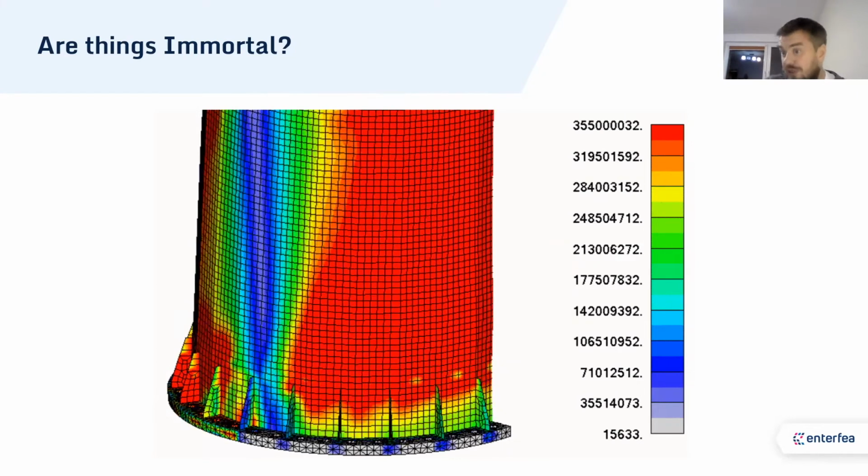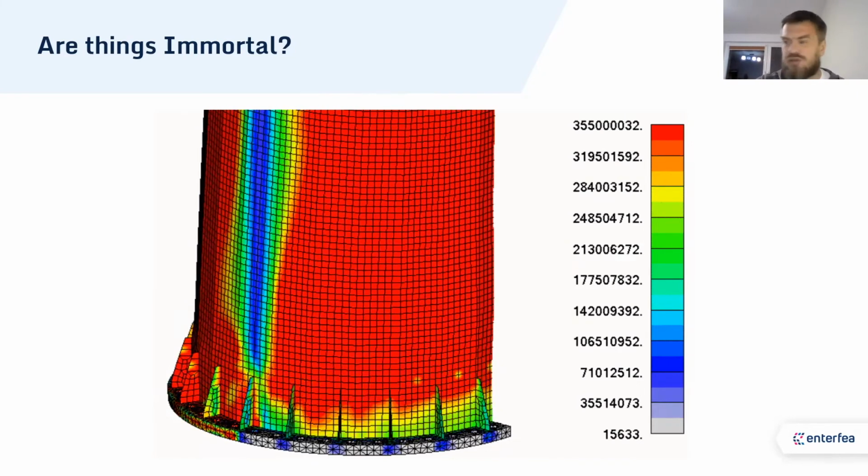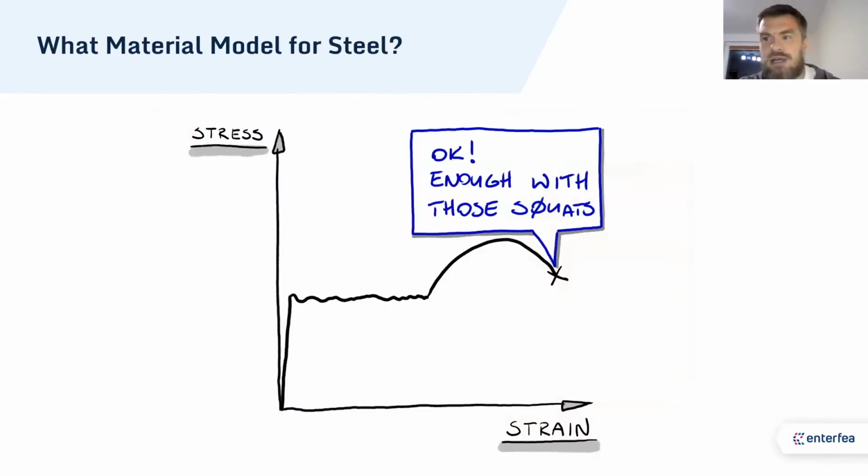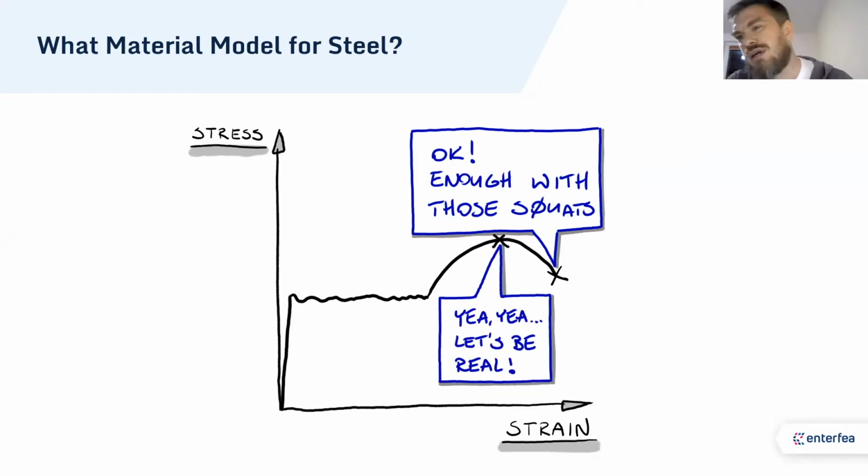So you could really, in nonlinear FEA, push your model to yield it completely. However, there is, firstly, a very practical thing. You can only have so much plastic strain because at the end, the material simply ruptures, right? So I can do the calculations and say, yeah, okay, I don't want to use elongation. Each steel has to have at least 15% of elongation before it breaks, but you know, 15 would be basically a toss of a coin, right?